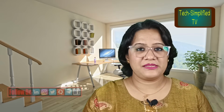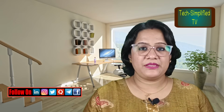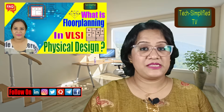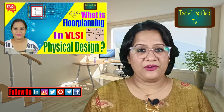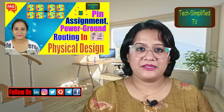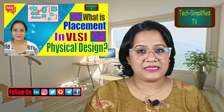I'm Munmun and today's VLSI Physical Design Marathon is your complete walkthrough of the back-end chip design flow. We will start with partitioning, that is, breaking down a big design into a few manageable blocks. Then we will move to floor planning to decide how these manageable blocks are placed to get the best usage of area and power. Next comes pin assignment and power ground routing that ensures strong connectivity and the most efficient usage of power connection. After that, we will dive into placement followed by global and detailed routing.